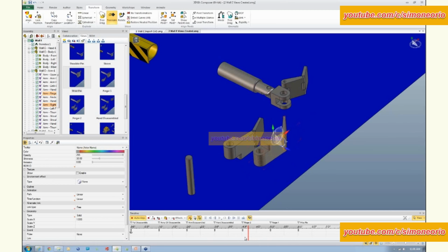And so what I'm going to do again is just hold my control key down. I'm going to grab the first key related to that, drag it about halfway. Okay, so now between 4 and 4.5 seconds, there's no motion occurring until I come out here and use my triad to actually overwrite that key at 4.5 seconds.